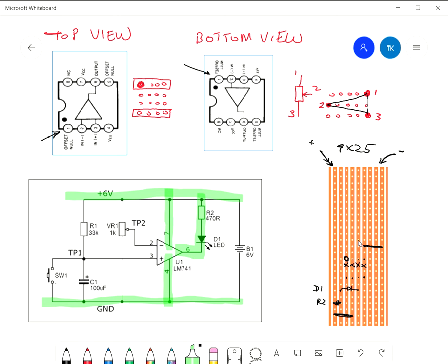We've got lots of space, so we'll connect pin 3, 1, 2, 3 from there to my, there we go, this is R1. Okay, and highlight there. So R1 now is connected from pin 3 to the positive rail.